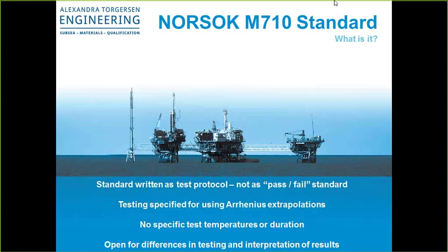So that means in order for that to succeed properly, you actually do need to test to a degree of degradation in order to do some serious extrapolations afterwards. The protocol does not specify test temperatures or durations. It's entirely up to the user to define these based on material type and application needs or understanding of the material behavior.